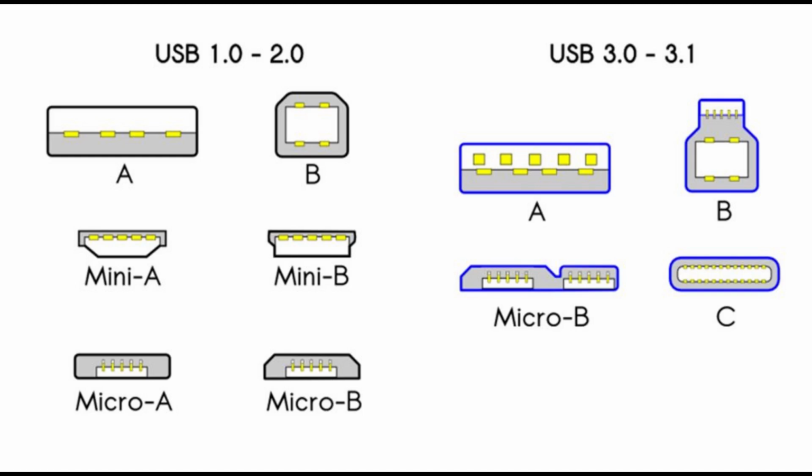SuperSpeed's architecture is full duplex. All earlier implementations, USB 1.0 to 2.0, are half duplex, arbitrated by the host. Low power and high power devices remain operational with this standard, but devices implementing SuperSpeed can provide increased current of between 150 mA and 900 mA, in discrete steps of 150 mA.